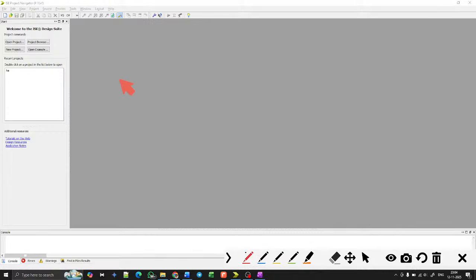First, you have to write down your VHDL program, which will be saved in a file which has an extension of .vhd. After writing down your program, we need to check its syntax, any grammatical errors. Then we are going to synthesize our VHDL program.